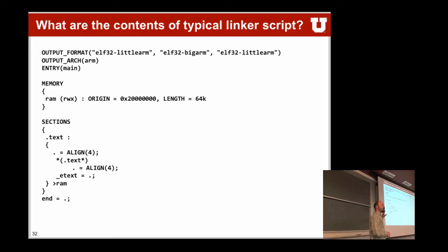We will look at more complicated ones later on and also in lab, where you can put stuff not just into RAM, but also into ROM. Usually into ROM, you only store stuff that's constant, so either executable or readable, but usually not modifiable, because modifying ROM is either impossible if it's burnt in, or if it's flash memory, you have to use specific functions to actually modify your flash. So usually ROM is only read and executable, while RAM is read, write, and executable.